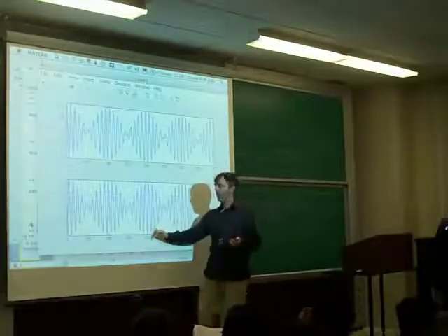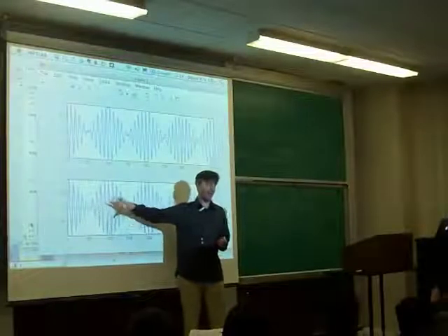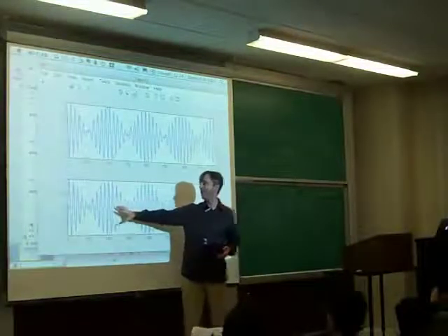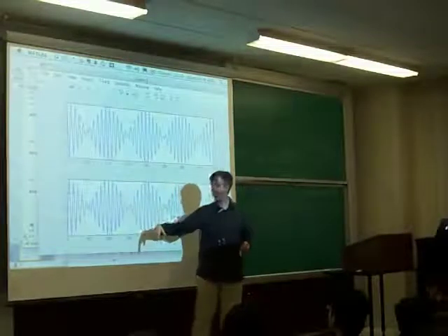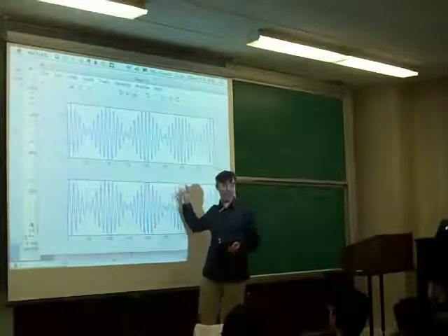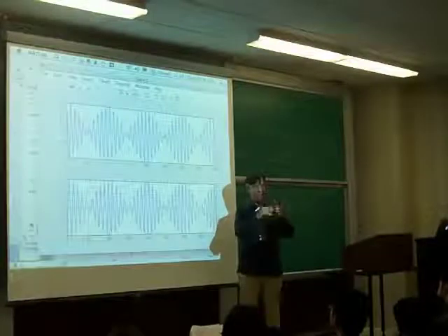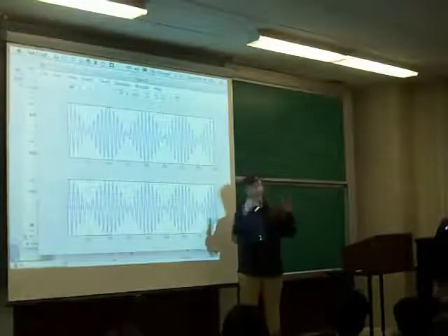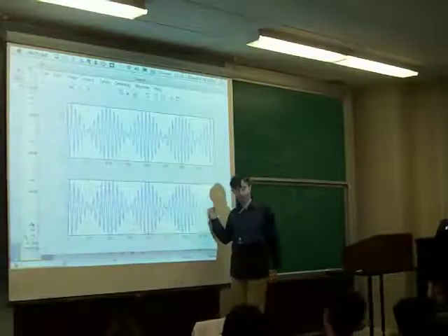If you've got a signal like this, an amplitude modulated signal, you kind of don't care what happens about the carrier. I mean, this is what AM radio is. You have some high frequency radio carrier, like 820 kilohertz or whatever, and you just modulate the amount of energy that you send down that thing. In the receiver, you have something which is tuned to that frequency, but then you just basically rectify it and low-pass filter it, and all you're left with is the envelope of the energy, right?